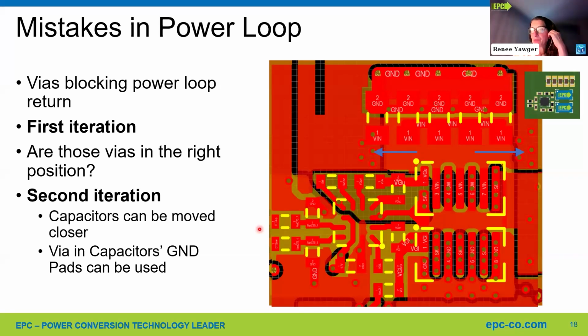Can turn off diodes be used if the gate driver does not have an independent low side pull down output? Yes and no. Recommendation is to use just a single resistor to be used as both turn on and turn off, as I was saying before.